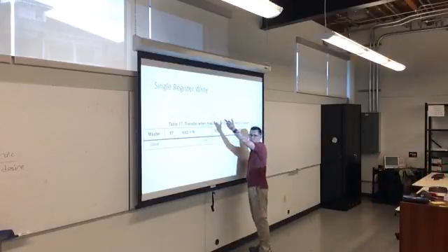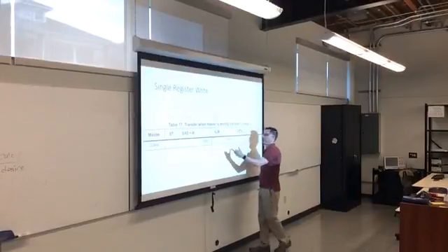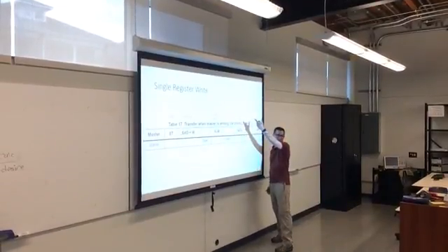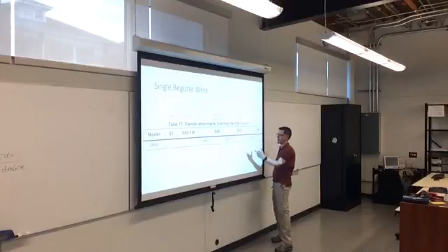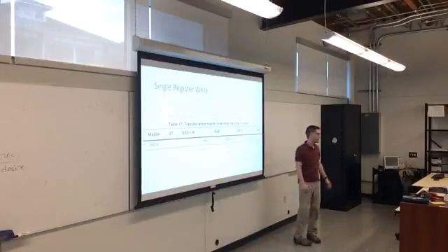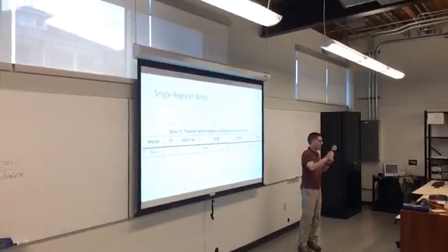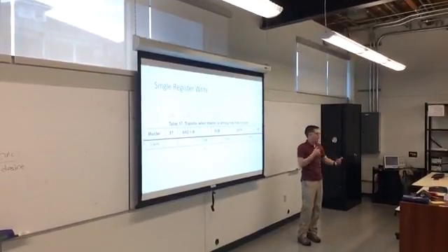So it's very similar to the SPI operations of, here's my address, here's the data, but you've got some acknowledgments in there. It's very similar, but instead of turning the chip select line up and down, you're doing start and stop. It's the same general idea. Questions on this? You need to understand this.